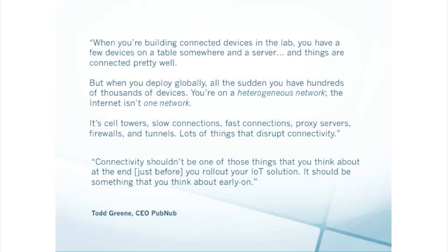Okay, so if you had to make a list of the core features to include in your IoT project, this is one that should be at the top of your list: connectivity. You might have to read between the lines a little bit here, but there are three takeaways that I see. The first one is to select frequencies in the ISM band that serve the largest possible audience. Here I'm talking about 400 megahertz, 900 megahertz, and 2.4 gigahertz. The reason is that he uses the term deploy globally, so that's where I get that first item from.